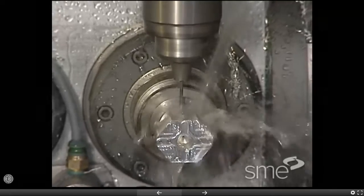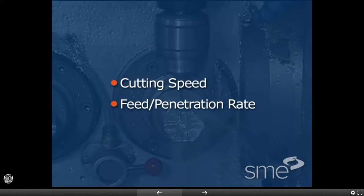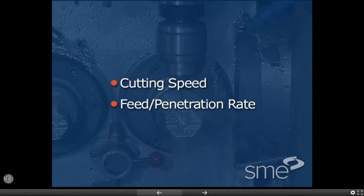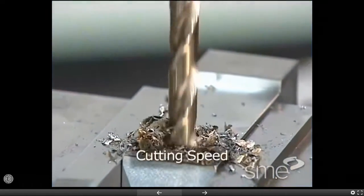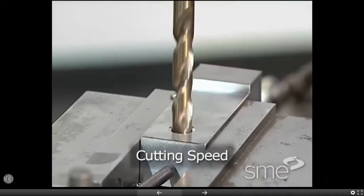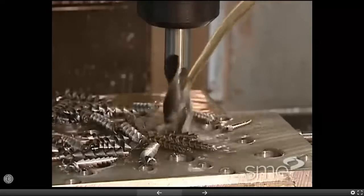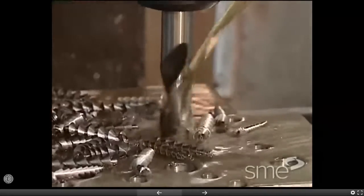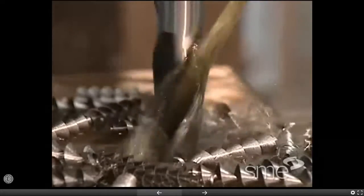The key operating parameters in drilling include cutting speed and feed or penetration rate. Drilling conditions influence these parameter selections. Cutting speed for drilling is measured at the periphery of the drill and is expressed as surface distance per minute. It varies from a maximum at the periphery of the drill to zero at its center axis.